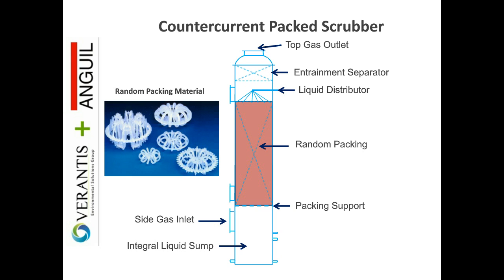velocities, high efficiencies up to and exceeding 99.99%, depending on what's needed and what the compound is, and pressure drops across the packed bed, let's say in the 1 to 4 inch water column range. So that's typically what we would look at with such a packing. Quite commonly for these applications, the performance requirements range from 95 to about 99.9% most of the time.